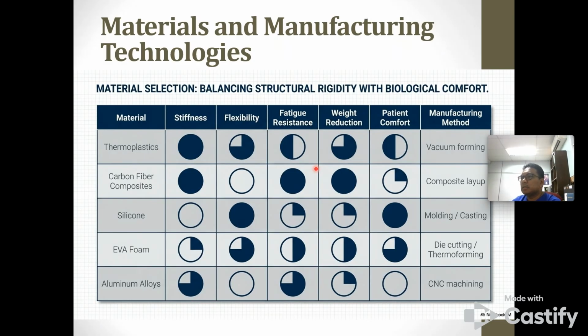And the material with high stiffness sometimes may also contribute to high mass. For example, if you have aluminium, it can contribute to high mass. But when you have composite, you know that composite is less weight but high stiffness, a high stiffness to weight ratio. It is very stiff, strong, but can reduce the weight.